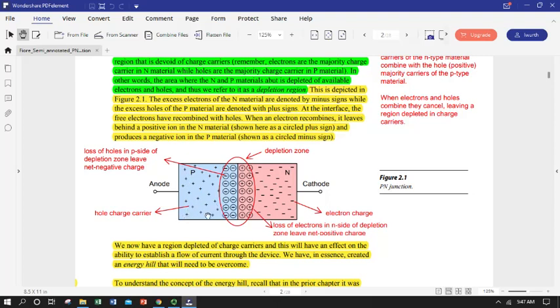silicon semiconductor, and so we're populating this side, literally this side of the chunk of silicon, with a material that, remember, has only 3 electrons when silicon had 4, so it's effectively rich in holes. So it's going to create a hole-rich P-type material here. So you can think of that as having a lot of holes to carry charge, because empty spaces in the valence band carry charge.